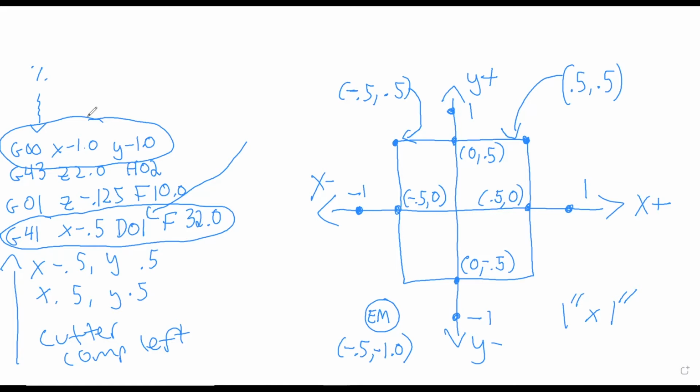Let me repeat that. We need to do a line movement at least half the cutter's diameter.